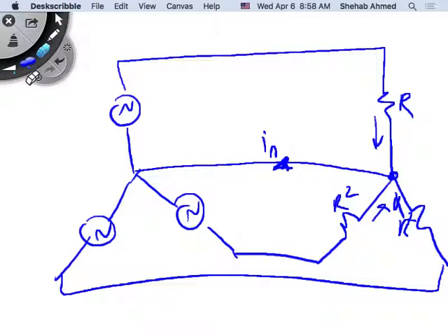if they're far away from each other, we would typically connect them through the ground connection, through a ground mat. So here in this building, we would have this neutral point that we have in this room connected to the neutral point of the transformer. Right? So think of this as this room, these three rooms. These three loads are the three rooms, the three lecture halls here. We would typically have the neutral point connected back to the neutral point of the transformer. So think of this as a transformer, for example. Okay?